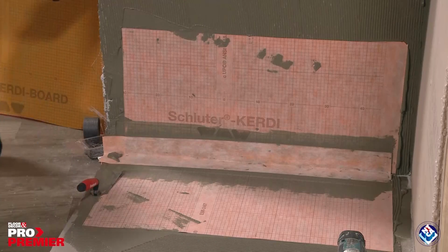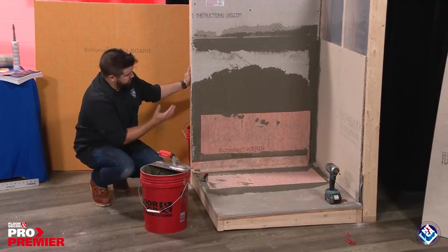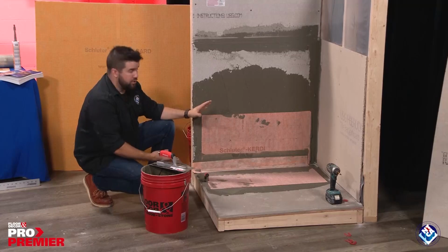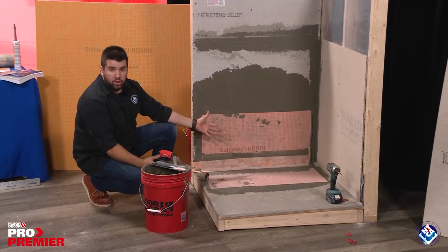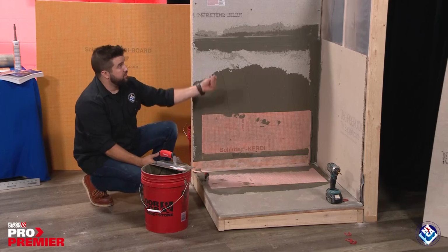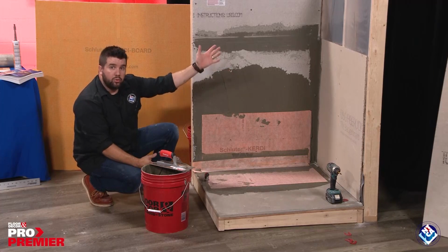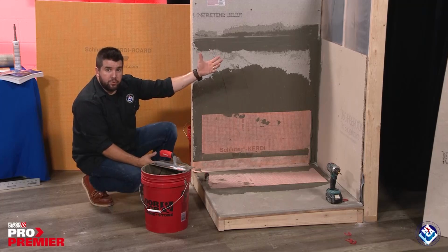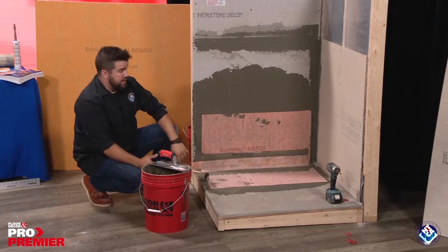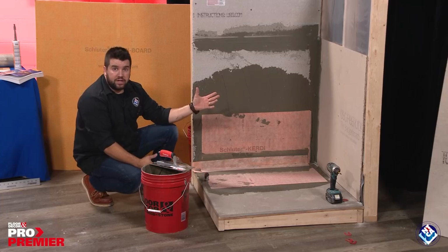So there we go, there's some membrane installed on the wall. So this is one option, again, membrane over top of a cement board. This is going to fall under one environmental classification. And over here behind the fiber rock, we have that 6 mil plastic, which is a vapor retarder, and that's going to fall under an environmental classification as well.